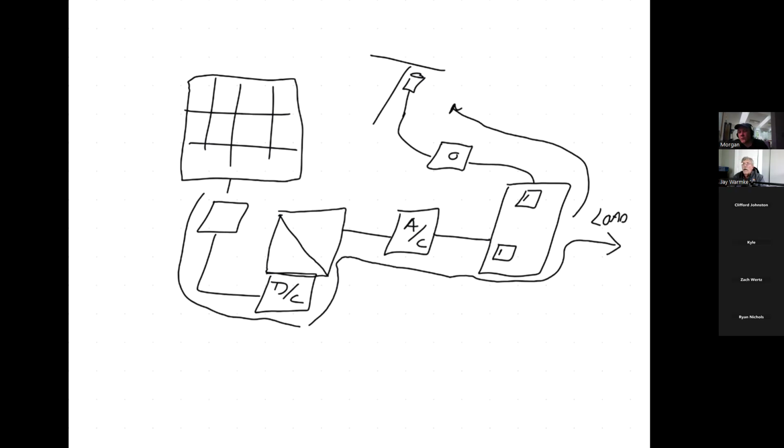Well, the old inverters were all designed that when they're turned off, when they're turned back on again, they go through a 5-minute handshake to make sure that they're syncing up with the grid signal. So it's almost like your modem's doing that boop, bump, all of that, where they're doing this handshake thing. But it was timed for 5 minutes, and all of the inverter manufacturers did exactly the same thing, 5 minutes to the second. Okay, so that's interesting.